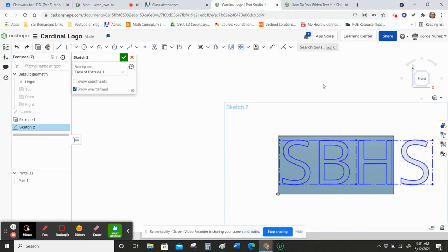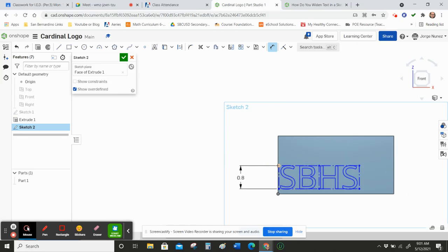Okay, if you want to make this bigger or smaller, the easiest way is to set a dimension. Right now, I know that my rectangle is 2x4. If I dimension my text, it's set to 1.52 inches. I want to make it smaller than that, so I can just dimension that block of text. Let's say 0.80, just a random number that's smaller. Actually, I like this as it is. It seems a good size. Let's say 2.5.